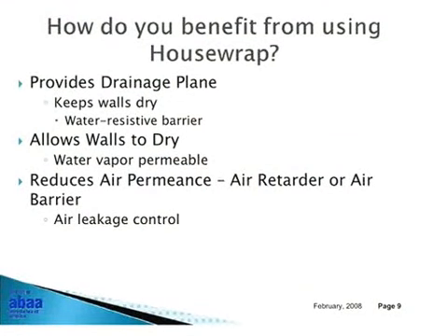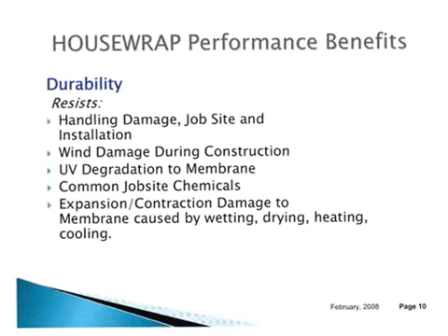Water vapor diffusion, again, allows the water moisture that's in your wall assembly to dry to the outside. It also is going to reduce the potential for wetting and increase the drying potential of your building assembly. With the water vapor flowing in the direction of drying, this will keep your wall dry over the period that you need it to do.